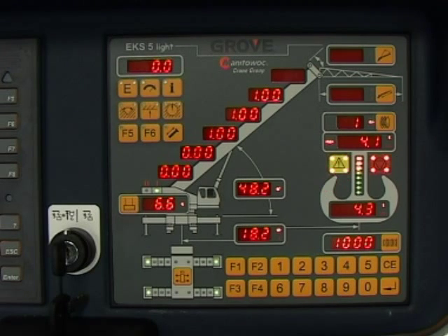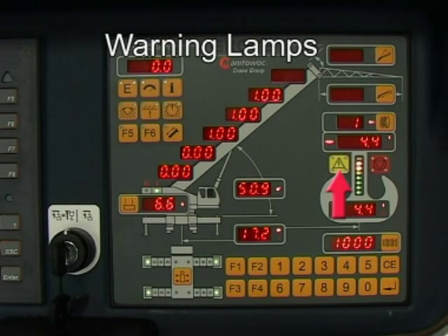The CE button is used to cancel the buzzer and acknowledge an error message. RCI pre-warning lamp. The lamp will light up at 90% or more of the permissible load. An intermittent warning buzzer will also be heard. RCI shutdown warning lamp. The lamp will light up if approximately 100% of the maximum permissible load has been reached,